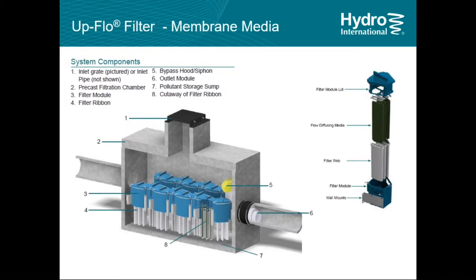The only difference is the inlet and the outlet can be at the same elevation. We really don't need 30 inches of head to operate membrane media. They can flow at a much faster rate. So we have to give a little more care to designing the actual flow rate / treatment rate for this application. So it still has a sump, so it operates very similar.